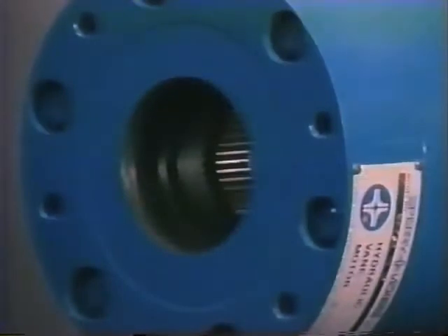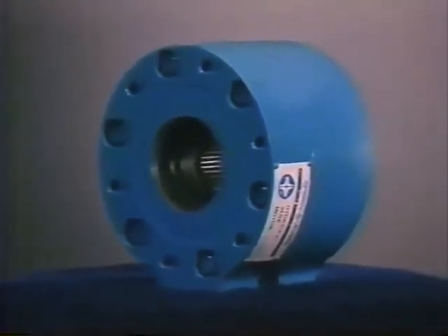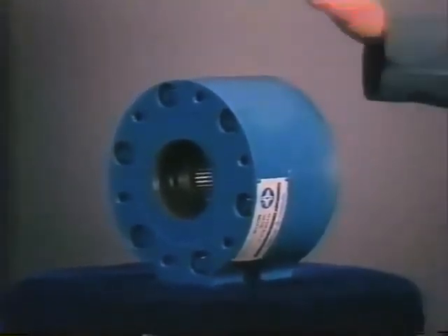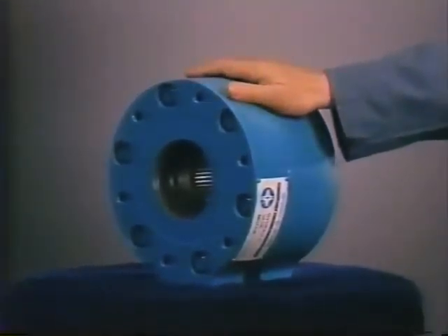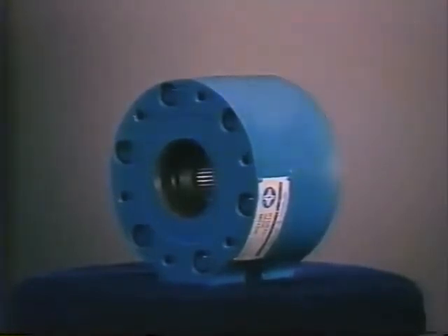We're now looking at what we call a high-torque, low-speed vane motor. This type, which is often used in applications such as an injection molding machine, has a maximum speed rating of 150 RPM and a maximum torque rating of up to 5,000 pound-feet. The capabilities of this type of motor often eliminate the need for a gearbox.